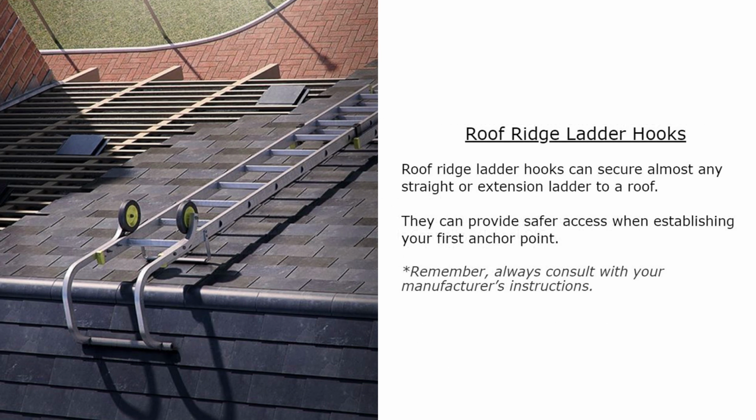Roof ridge ladder hooks can secure almost any straight or extension ladder to a roof. They can provide safer access when establishing your first anchor point. Remember, always consult your manufacturer's instructions.